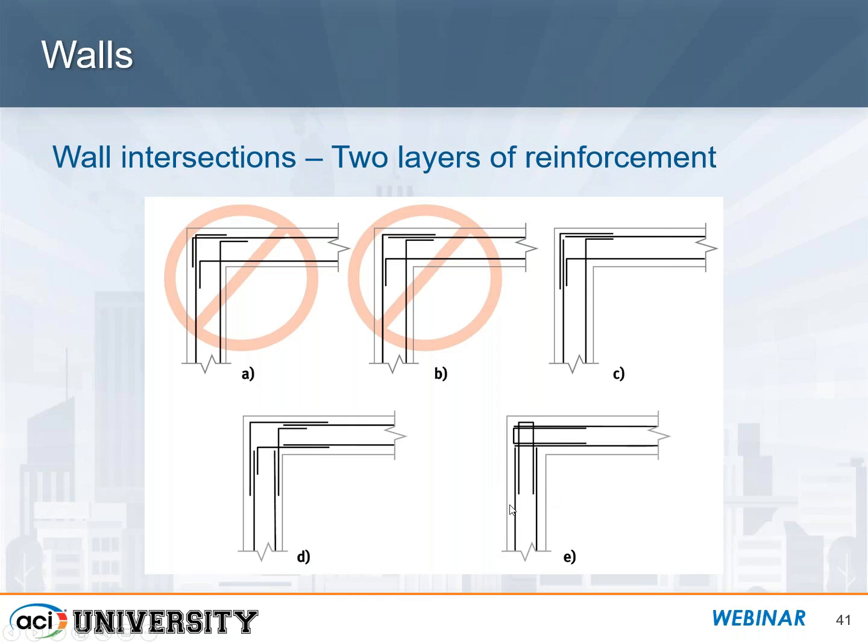Now, if your wall is thick enough, you can provide these hairpins in either direction. And again, you have nothing but horizontal bar. Imagine this cage being dropped in first and this cage being dropped in second. Then you can provide these hairpins that get installed and tied to these pre-assembled cages. And it's a very simple thing to do in the field. Now, you have to have a thick enough wall in order for those hairpins to be developed. But if you do, this can be a very advantageous solution for this type of construction.